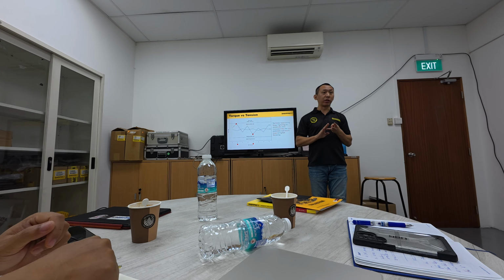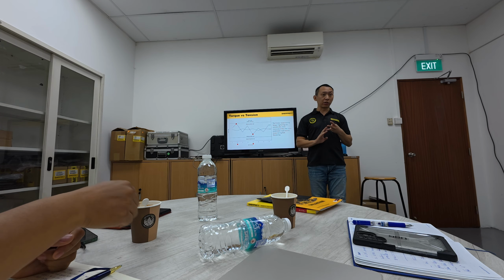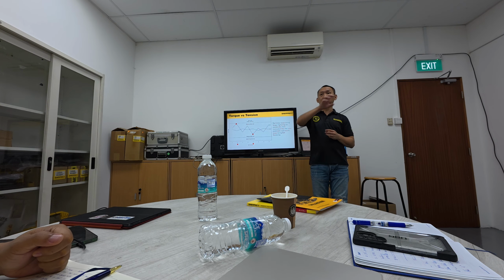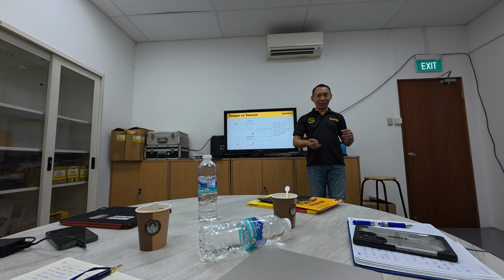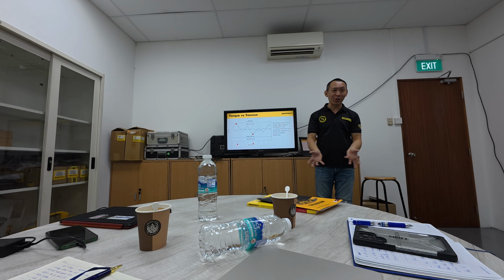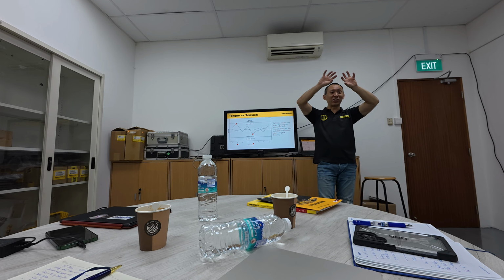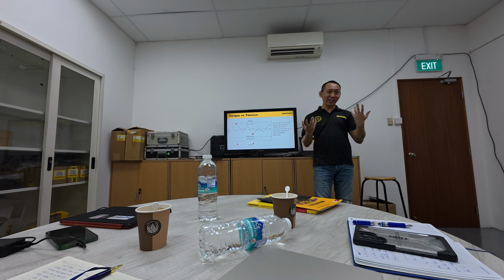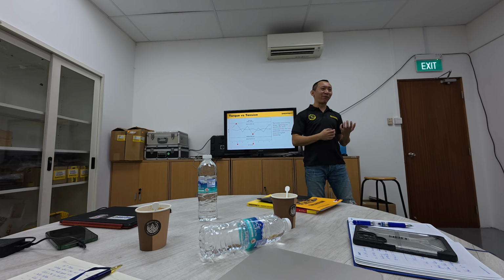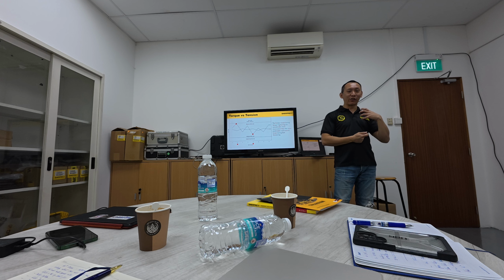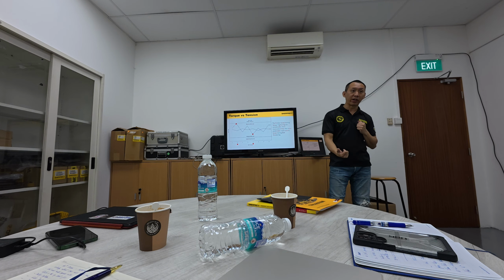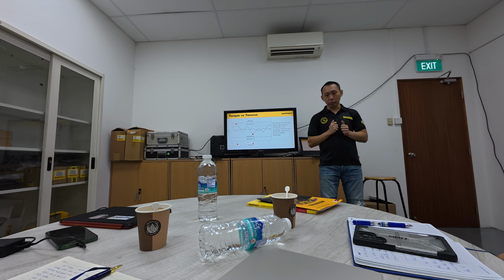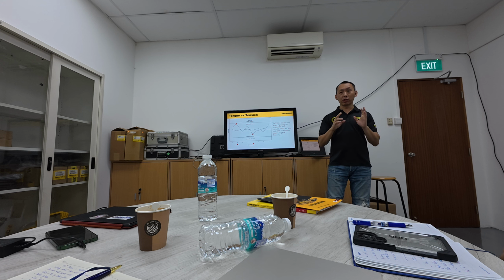Time is also a factor, because they want it to be fast. There are a lot of ways to do it. If you want it fast, they can buy 4 torque wrenches and operate all 4 at the same time. That will be very fast. Or they can do 100% with one tensioner to one stud. That can also be very fast. So it really depends on the budget and the timeline they are looking at to maintain the tool. Because for the tensioner, the setup is very simple, just put a tensioner on the bar, but torque wrench.